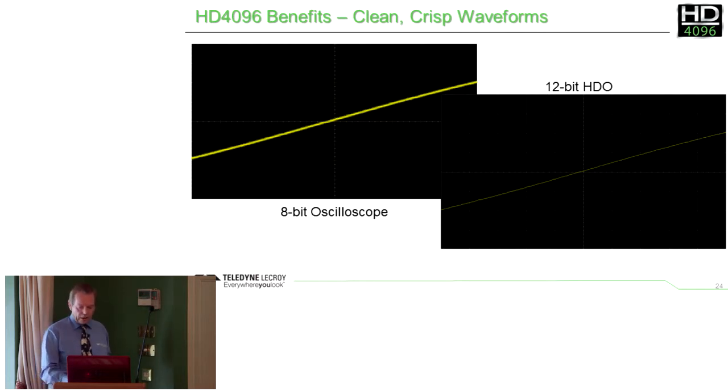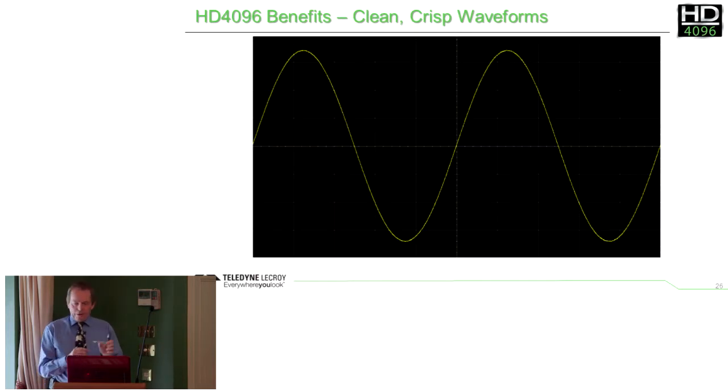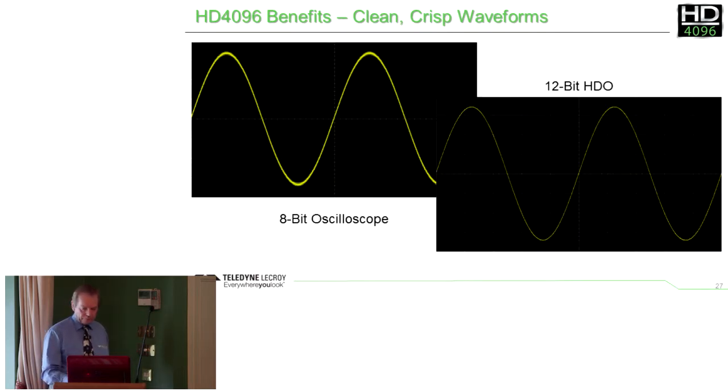A lot of scopes are having these features these days where they're saying they've got built-in multimeters in them. They've got a little display on it, says it's a built-in multimeter, but that's typically using the accuracy of the 8-bit A to D. So they're not actually very accurate. Whereas with a 12-bit, doing that kind of thing, you get a lot more vertical measurement accuracy.